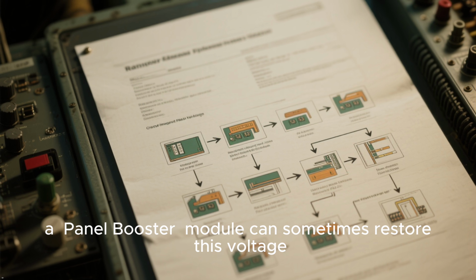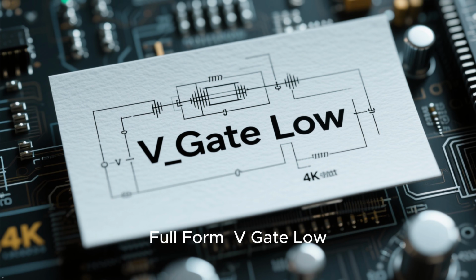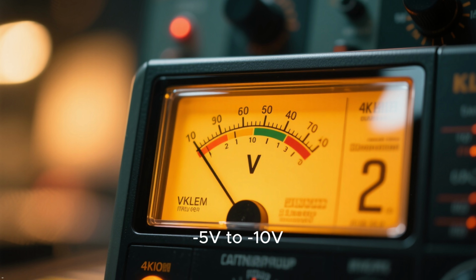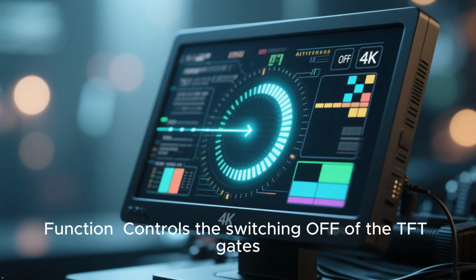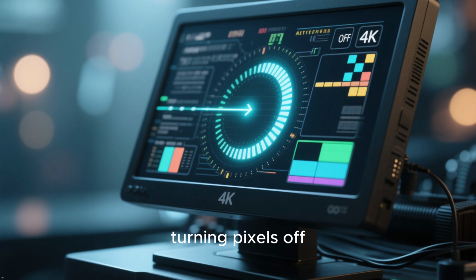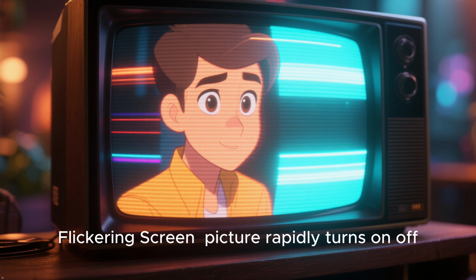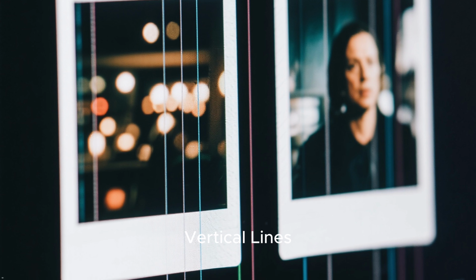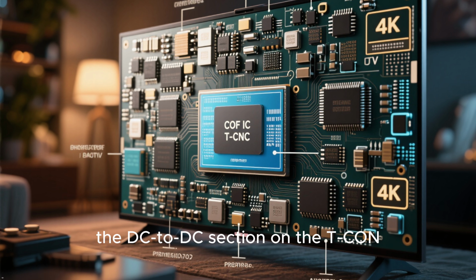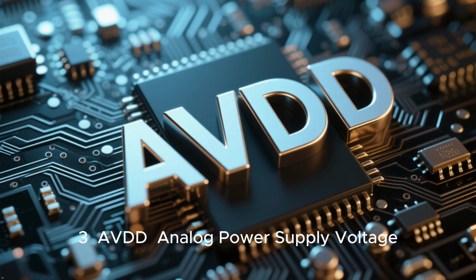Externally, a panel booster module can sometimes restore this voltage. 2. VGL, low gate voltage. Full form, V underscore gate low. Typical value, -5 volts to -10 volts. Function: controls the switching off of the TFT gates, turning pixels off. Symptoms: if missing, no display, flickering screen, picture rapidly turns on and off, vertical lines. Repair approach: focus on the COF IC, check for shorts, the DC-to-DC section on the TCON, and associated capacitors on the VGL line.